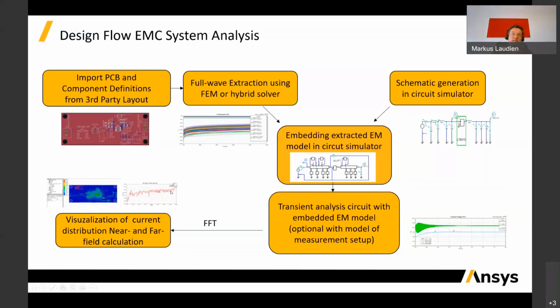In this case, for example, it's a near field at 3-meter distance over frequency. This means every frequency point then needs to be solved, and the radiation from the board or the device under test will be evaluated, either with antenna or without, or just by calculation from Green's function. This is the design flow.